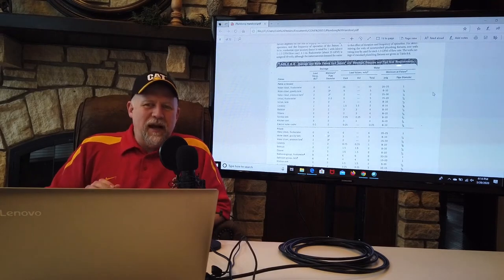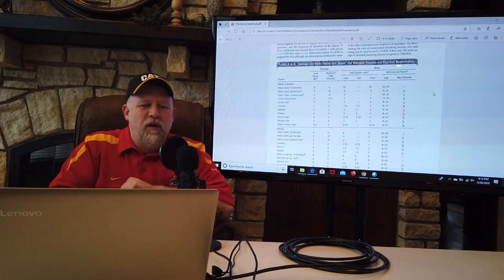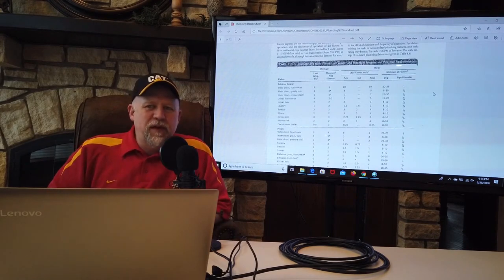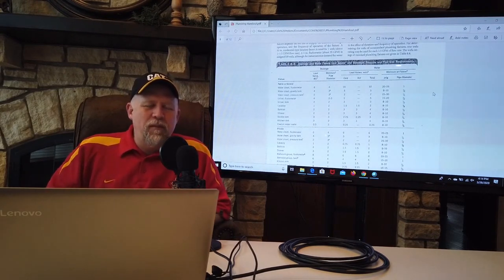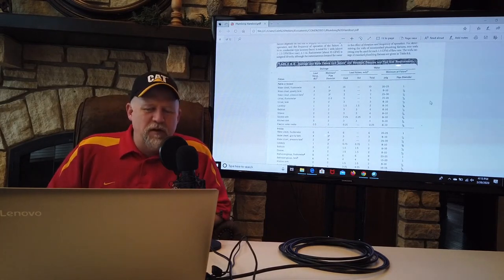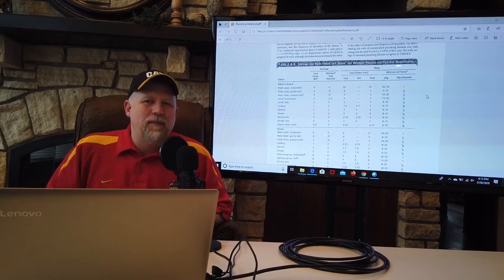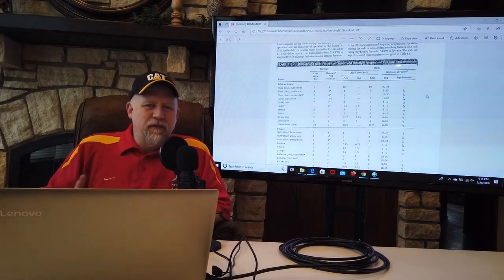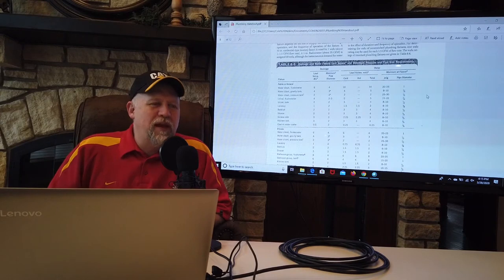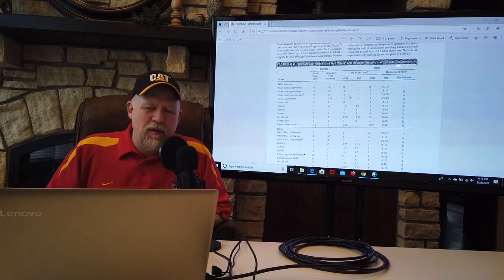When I say they're averages, you can't just take the peak flow rate for all the different fixtures and add them up. That won't make any sense. You will end up with a sewer main and a water main far too large. And the truth is, not all of the water closets flush at one time. So there's got to be some diversity to account for that rate of use. And that's where drainage fixture units and water supply fixture units come in.